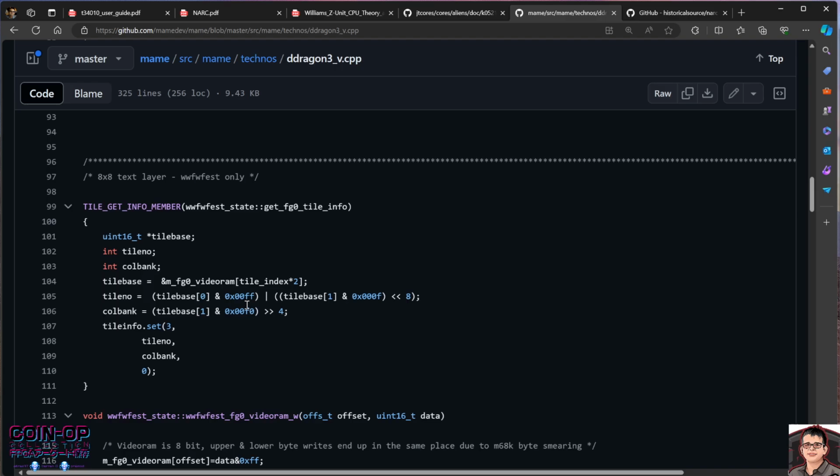Now, how I draw things, which is how the boards usually do it, is through line buffers. So we draw things line by line. You can't draw a whole tile or a whole frame. I mean, I guess you can draw a whole frame at once, but that's not how the boards usually work. Usually the boards work by drawing line by line. So you're in the horizontal blanking area and you're buffering 1 or 2 lines ahead, sometimes 3 or 4 lines ahead, right?